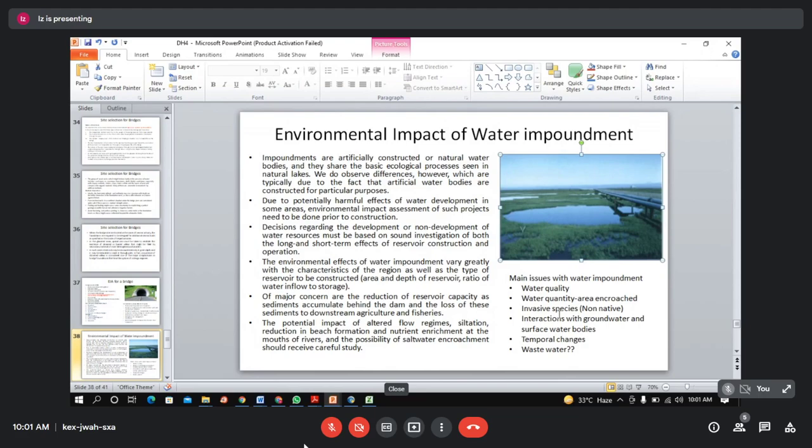For example, it may harm the water quality. So very first thing you will include what is the water quality of this water impoundment, and how it will interact with the groundwater, or how it interact with the existing surface water bodies if it is, right? And depend what will be the extent of impoundment, that means how much area will be impounded. Impounded का मतलब समझ रहे हैं, मीन्स कितना एरिया इनंडेटेड हो जाएगा, पानी से भर जाएगा, inundated हो जाएगा, how much area will be inundated. So that means that much area will be excluded from city planning, right? And what will be the thickness or the volume of water, and how it interact with rest of the environmental domain. So this you need to establish within the EIA, right?